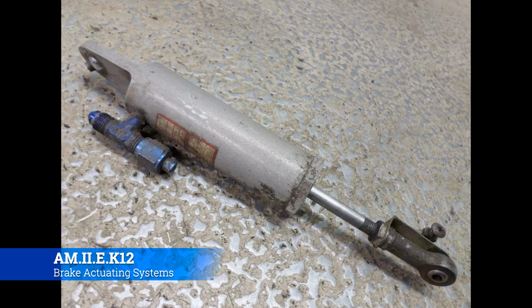You can start to see the sacrifice that you have to make in the travel in the master cylinder to the actual travel that you get on the slave cylinder downstream. That sacrifice allows the mechanical advantage to take place. You also want to look at the differences in the cylinder size. Now, that master cylinder's not very big on the inside, but the actual brake cylinder in the housing is probably about 2.5 inches in diameter. It's fairly substantive.